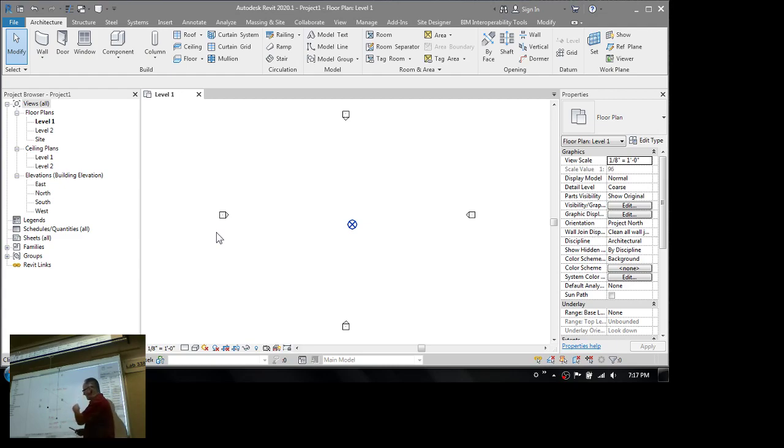The problem with DirectX is that it has a finite coordinate system, a finite number of integers with which it can show data on your screen. Revit's own internal coordinates are just as accurate as AutoCAD, so they call it floating point precision. Don't worry about what that means, it's super accurate. But DirectX begins to fall off the wagon once you get a long way from this 0, 0 point.